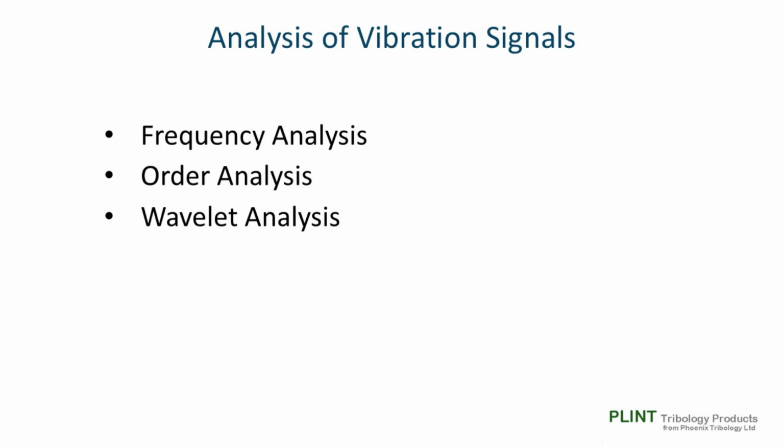Then there are more complicated forms of analysis such as model-based analysis. Hence we really need to decide what it is we want or think we need to measure when it comes to vibration measurement and analysis. Then choose an appropriate bandwidth sensor, then choose an appropriate analysis system. It is not enough just to data log some parameter. We really need to know what the signal means and how it is to be interpreted.